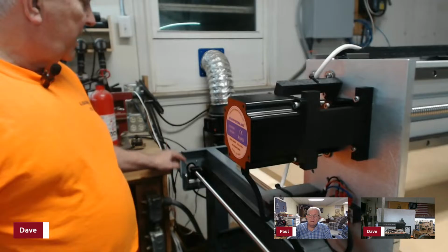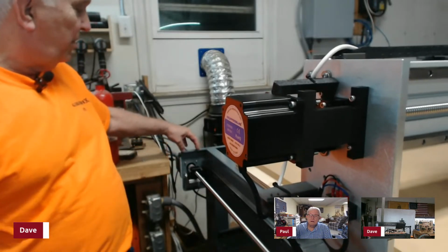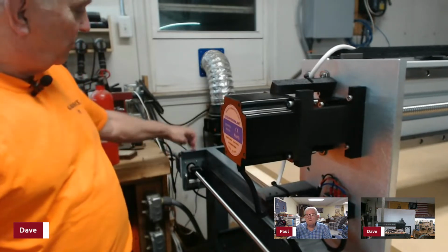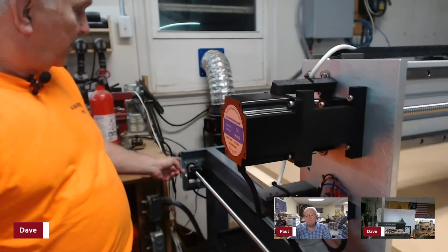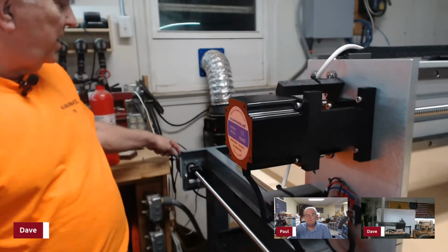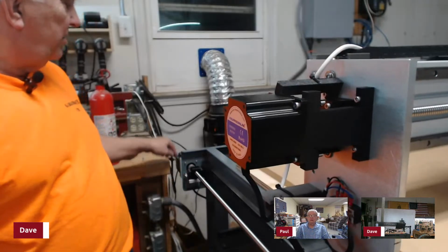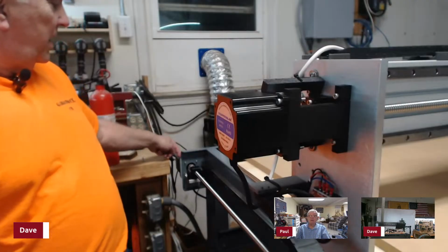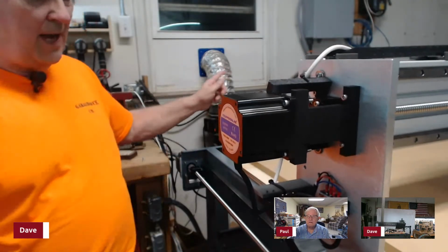And then the NEMA 34 is basically fastened to the same place. But these holes are for NEMA 23s, which were in this originally. So I bought an adapter plate that converts NEMA 23s to NEMA 34. So you bolt the plate on using the NEMA 23 holes, and then you bolt the NEMA 34 stepper into tapped holes in that plate. So I had to do that 2 times.